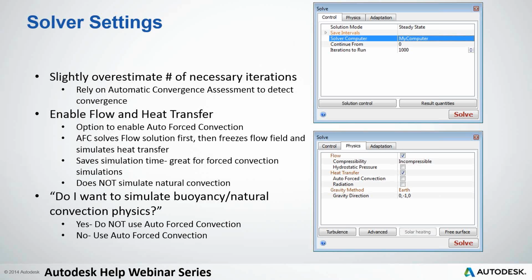Now, when I'm just doing rough design scenarios, if I have 5 different ones, I always just go with the default convergence criteria. If you narrow your design down and really want to pinpoint chip temperatures and things like that, then you tighten your convergence criteria. But to do it to all 5 is definitely going to waste time and resources.